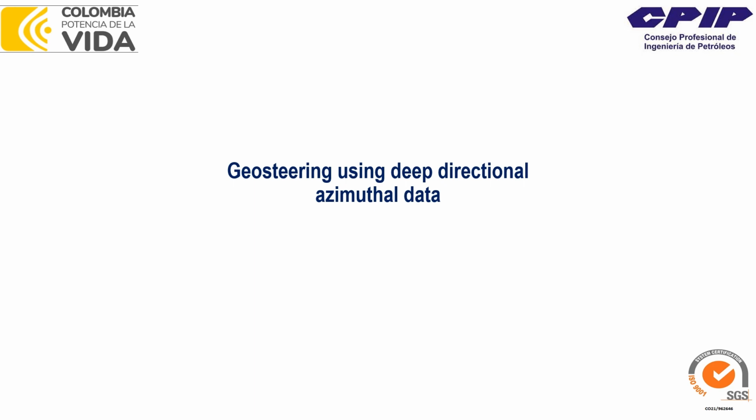And that's honestly like a new page in geosteering for the entire industry, which started in 2005 when the first deep resistivity tool appeared in the market. Together with this deep resistivity tool appeared the concept which is called proactive geosteering, in contrast with reactive geosteering.